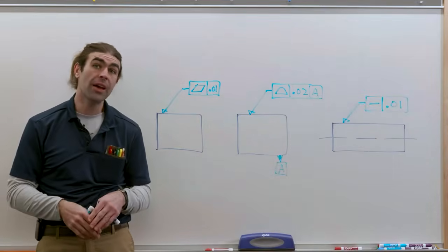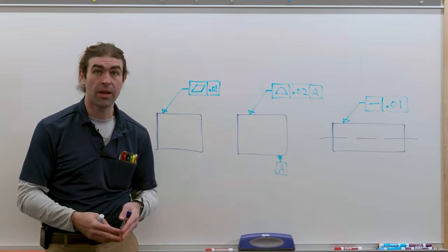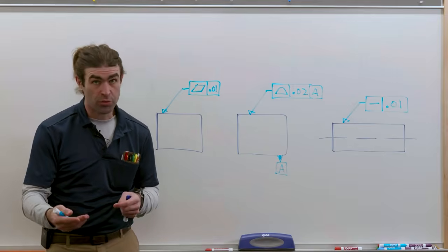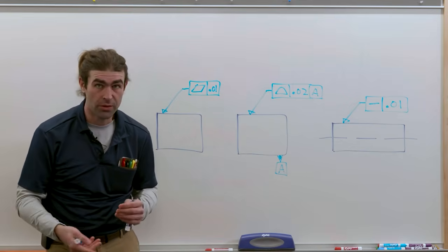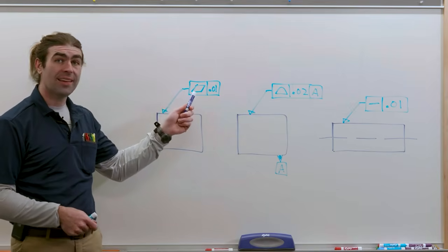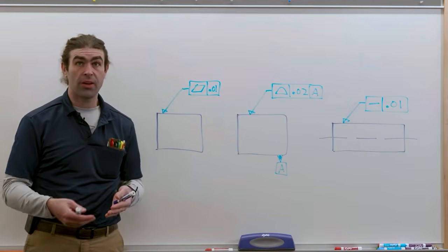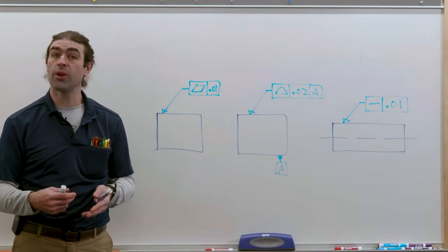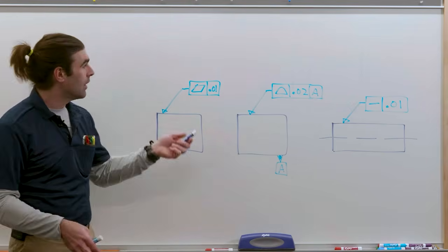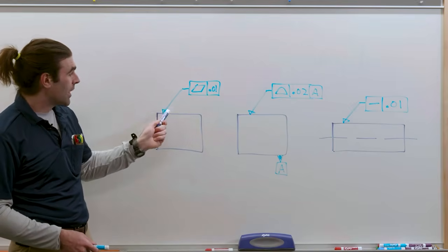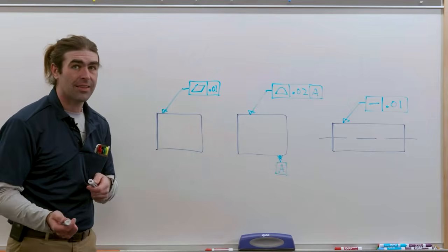So feature control frames differ depending on how they're applied, what geometric characteristic is applying, and how many datums there are. Now, there's more videos I've made about this, specifically the different kinds of geometric characteristic symbols, but let's just talk about a few. First is form tolerances, like flatness, which typically or never have a datum reference. Because form tolerances only apply to individual features, there's never a need to relate them to anything else. So in this case, a flatness tolerance is directed with a leader to a surface. It's just saying that surface is flat to within 10 thousandths.